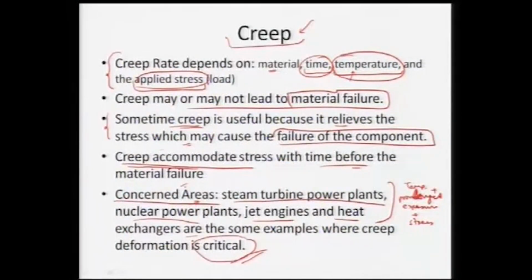So, in this case we have to control the creep by designing, proper selection of the material, also calculating what is the temperature, what is the time, and what is the stress level that is acting on that particular component. So, we can utilize certain design concepts of controlling the microstructure as well. By altering the microstructure, we can also control creep in certain sense, or by controlling the stress or temperature also we can control the creep.